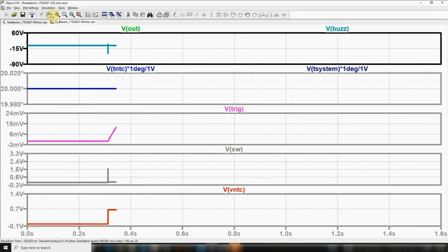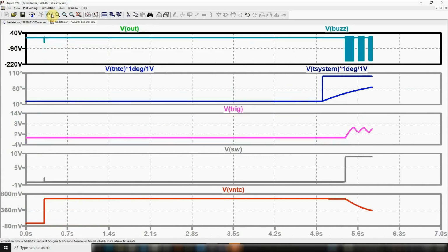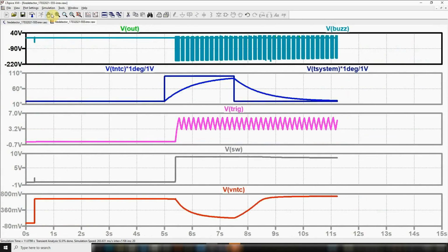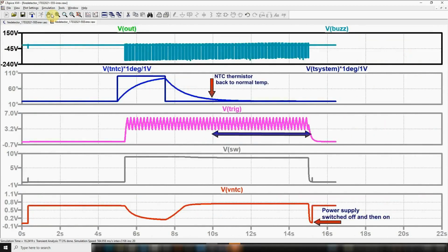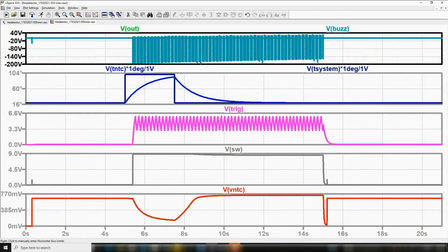The detector is switched on. The temperature is going to increase now. So we see effectively that the alarm stops only when we switch off the power supply, long after the thermistor is back to ambient. This brings more security to the heat detection for the case where the thermistor would go into open circuit after the alarm has started. A manual switch off of the siren is in this case necessary.